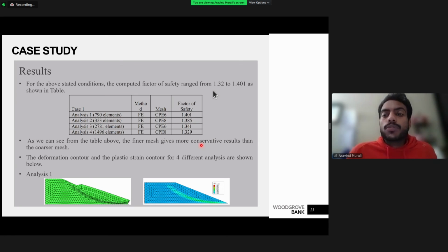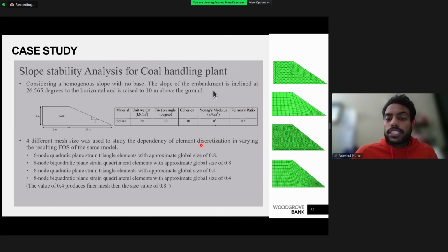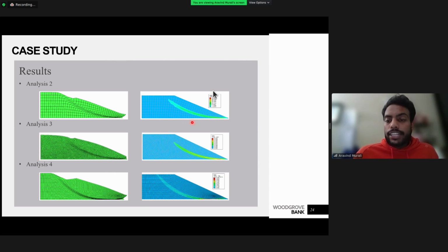Also, the analysis was carried out by installing a soil nail and checking the efficiency of the soil nail installation in increasing the factor of safety of the slope. For the case of a 10-meter long nail, it was not long enough to connect the slipping wedge to the remaining body of the soil sample. Therefore, it did not improve the deformation considerably. When the slope did not have any reinforcement, the obtained factor of safety was around 1.4.